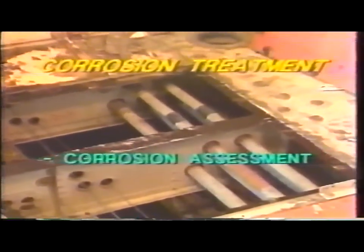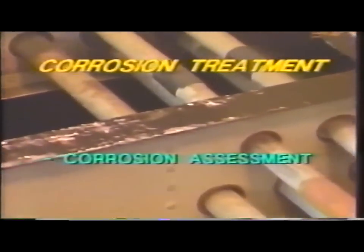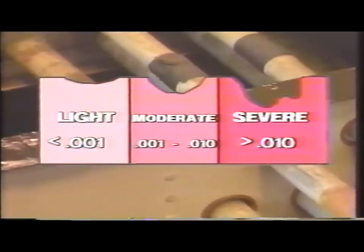Corrosion damage assessment is required to determine whether the necessary repair and rework is within the limits set by the manufacturer. The first step in assessing corrosion damage is to classify the corrosion as light, moderate, or severe. Let's look at corrosion assessment of aluminum.